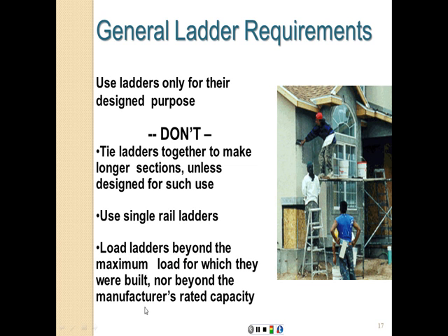Each ladder comes with a sticker on the side showing its specifications and the maximum load that it should support. What we have here is an improvisation. They're using the ladder as a platform for a platform, and it's very unstable, and that doesn't show proper maintenance or proper use of the ladders.